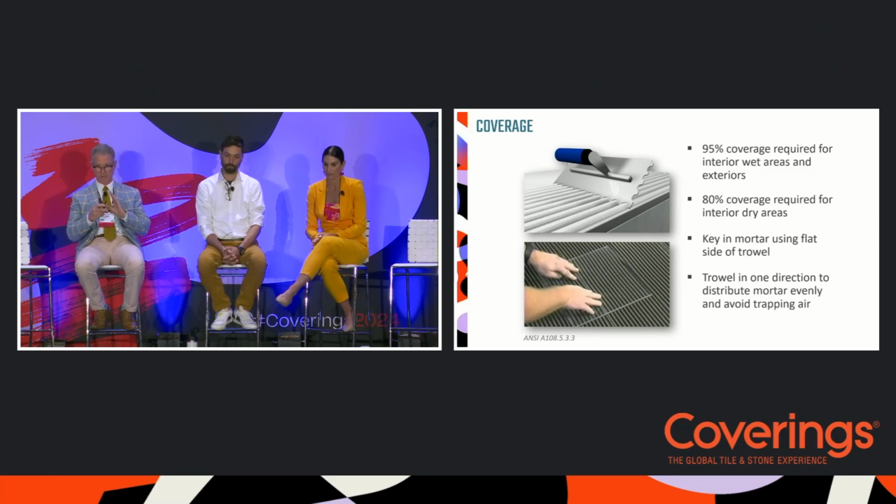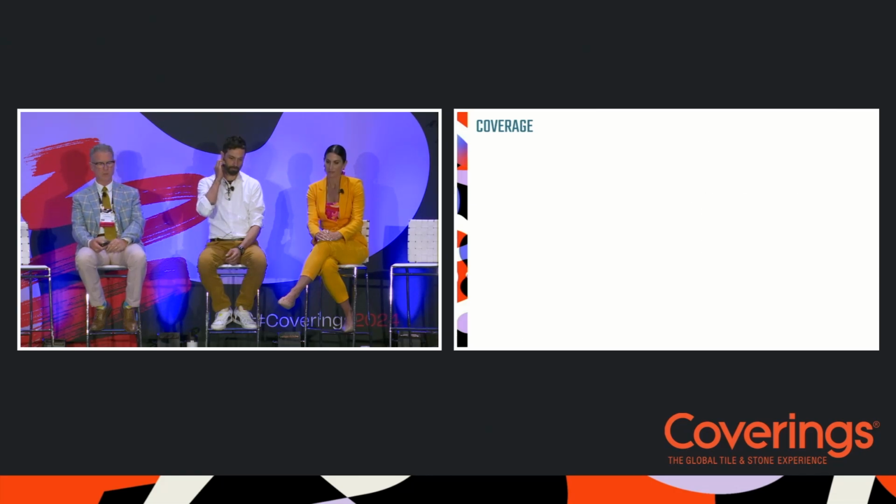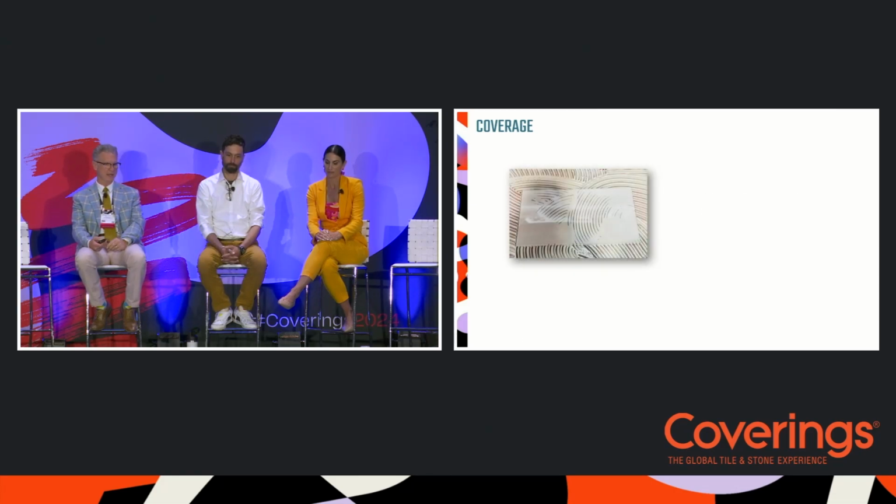All right, I've been promoting to change the term coverage to coverage and embedment, and I think people look at me funny because it's too many words, but you can have 100% coverage, but if you don't embed the tile in that 100% of mortar, it's not really considered 100% coverage. So what the ANSI standards tell us is that 95% coverage and embedment is required for tile laid in wet areas. 80% coverage is the minimum coverage that we need for tile in non-wet areas.